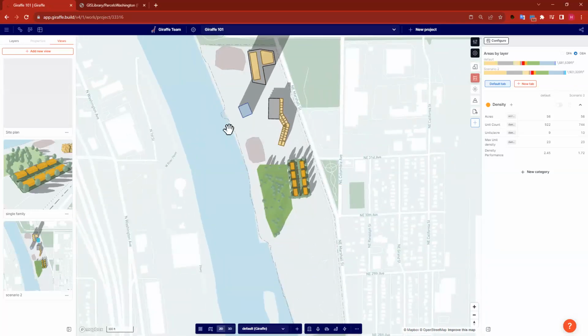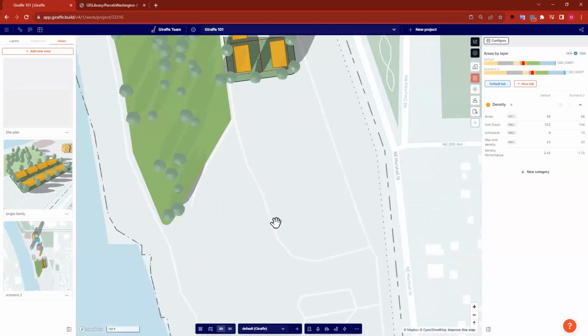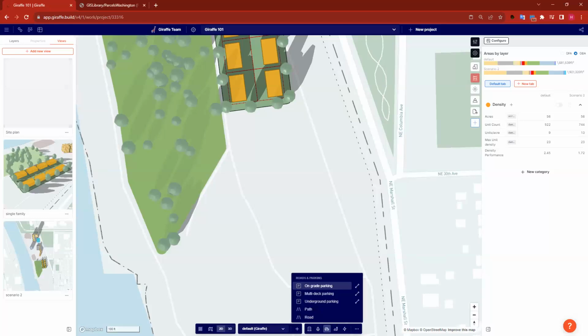So the second part of the question is bringing your specific unit layouts into the apartment tool. I wouldn't recommend doing it exactly how you've written it in your question, and maybe I'm just misunderstanding your question. But if you have a pre-existing building layout that you use over and over again, and you want it to be a template that folks can use, I would actually recommend drawing it manually, grouping it, and leaving it in your design library template for them to just grab.